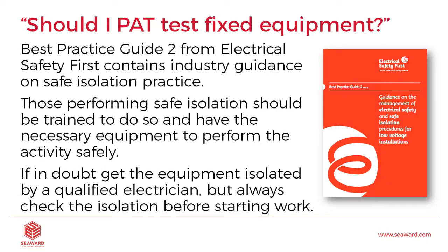So moving on from there then, the fixed equipment testing itself, there is a best practice guide 2 from Electrical Safety First, which contains industry guidance on safe isolation practice. Again, it's a free download off the Electrical Safety First website. And those performing safe isolation should be trained to do so and have the necessary equipment to perform the activity safely. If you're ever in doubt, get the equipment isolated by a qualified electrician, but always check the isolation before starting any work.